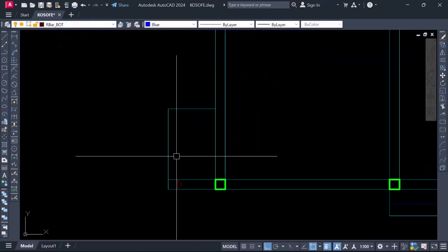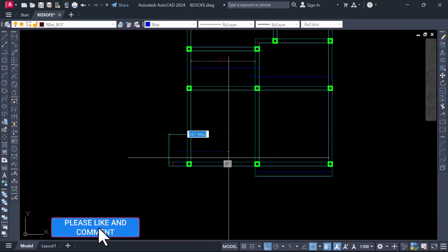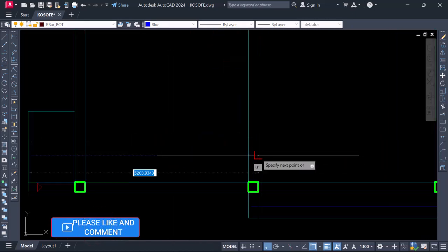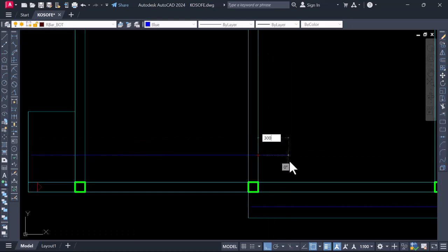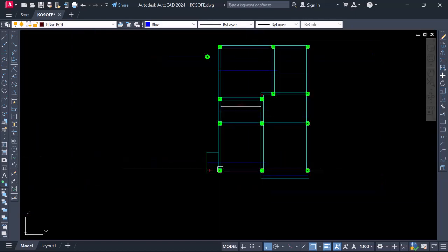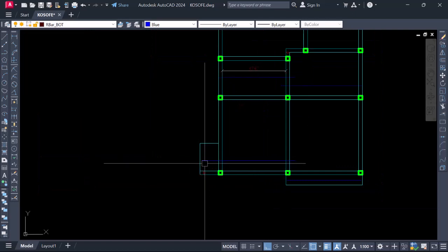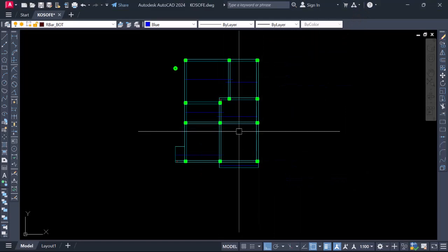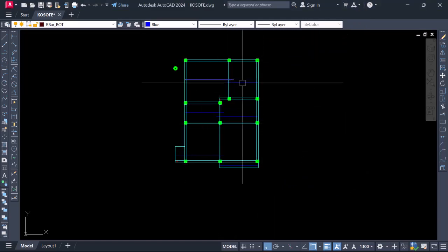So in the bottom reinforcement too, we're going to create the bottom reinforcement over here, and we're going to lap our bottom reinforcement here, and we're going to extend it 30 away from the beam, right? From the beam. You don't want to support your reinforcement at this beam joint. You're going to exceed by 30 millimeter. And in doing that, you join so that they will have the same line, right? So this is extending from the cantilever out. You understand?